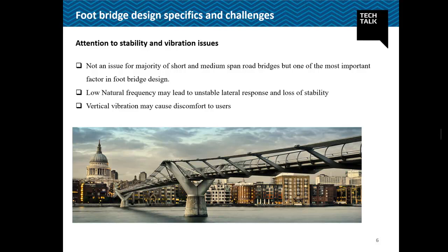What happened was that the bridge lurched to one side. Due to the lurching of the bridge, the pedestrians changed the way they walk in anticipation of the bridge movement. To balance themselves, they spread their feet apart, causing a lateral force on the bridge. All the pedestrians standing on the bridge did it at the same time, which caused a synchronous lateral excitation.